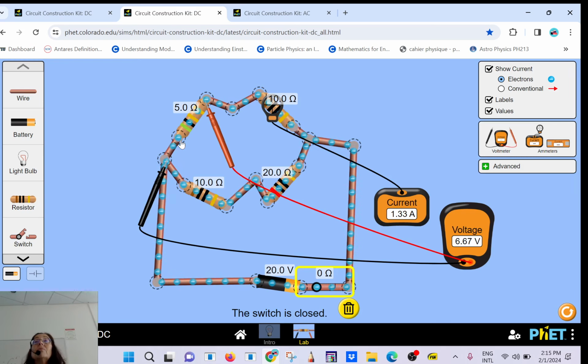So if I ask you for the test, if you take a voltmeter and plug that into your outlet, so you have the hot wire and the return path, you're going to get what is called the RMS, the root mean square voltage. So it's like an average. So what's going to be your reading? 120 volt AC.